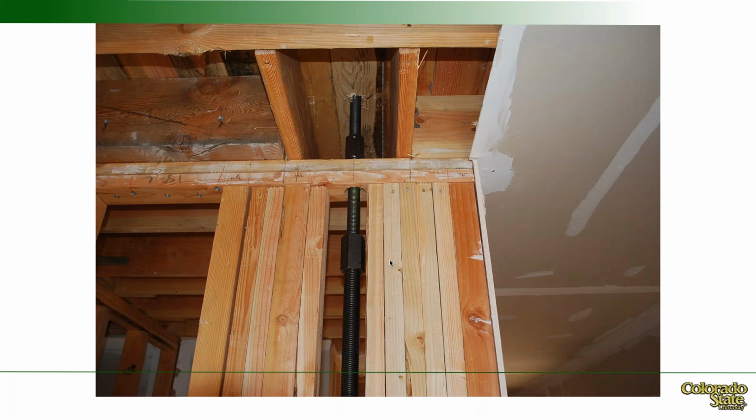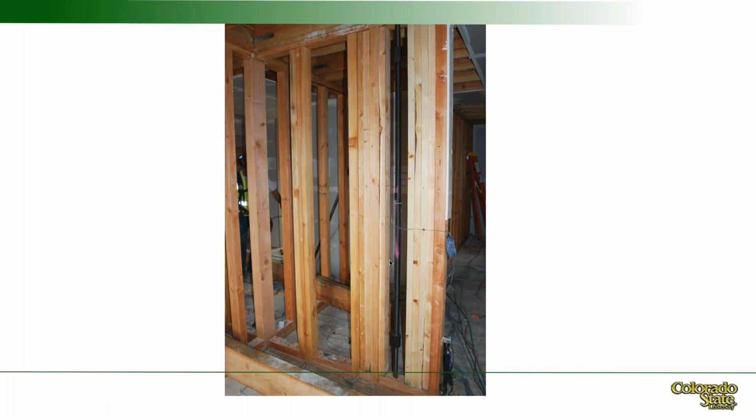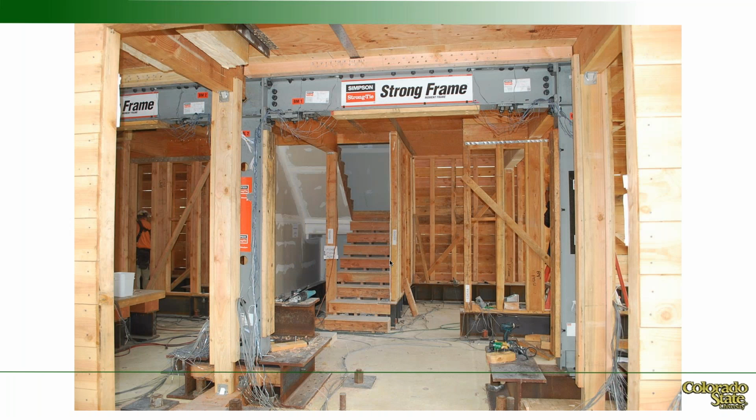And here you see one installed, and you can see the toenail stud packs that were put in for compression. So this is looking up at the ceiling level, probably on that second floor. And then here you see a little clearer shot. And then this is back down on the first floor level. And so that wall you were seeing, and just above the moment frame, you can see the shear transfer done with self-tapping screws.